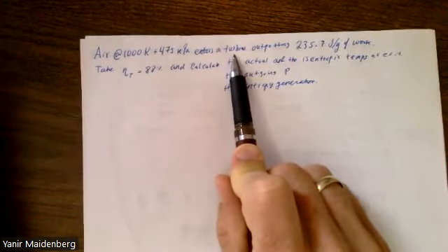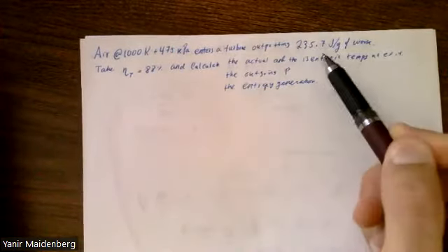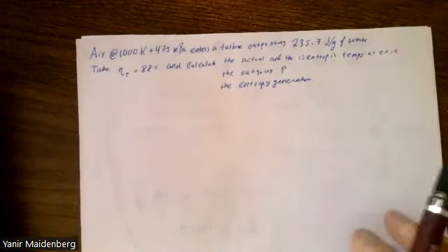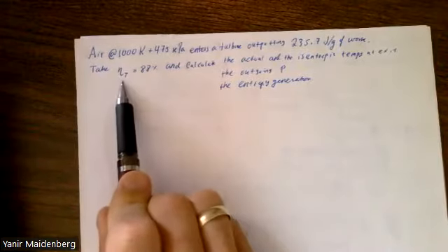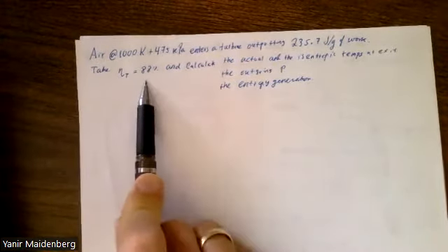It produces work by flowing some sort of a gas through it, and as the gas is expanding through the turbine, it moves some sort of rotor or some sort of blade, and it does work for us. So it's going to output this much work as a result of the gas expansion within it. And we know that the isentropic efficiency is 88%.